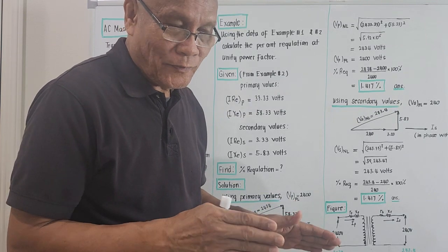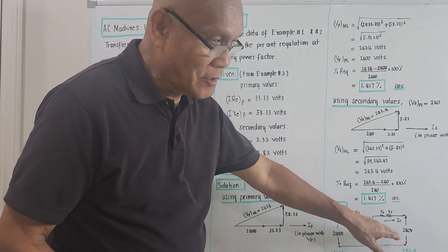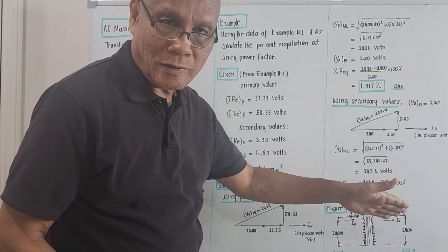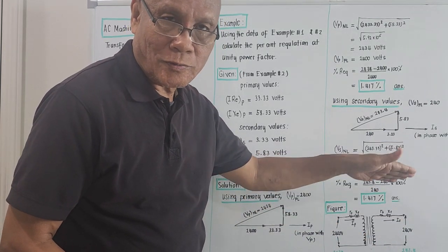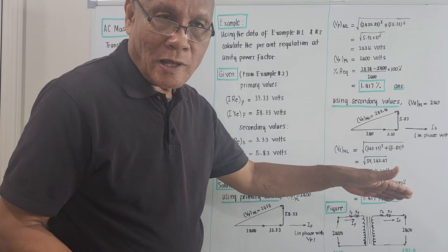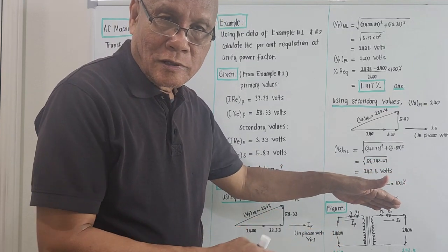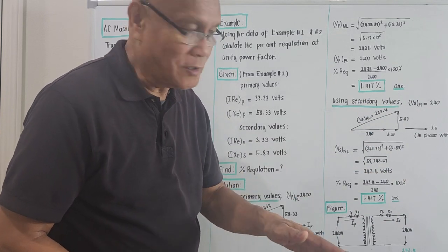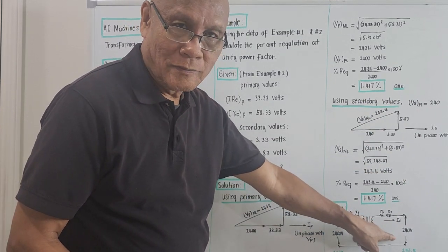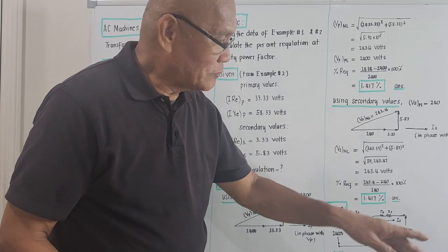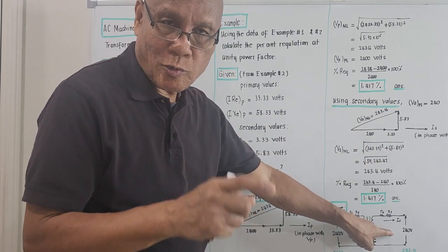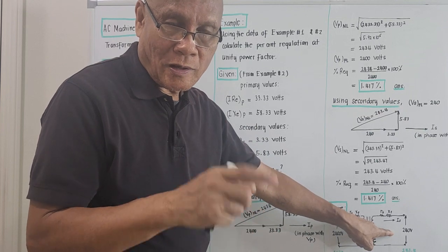So the given value should be higher than 240 at no load, then at full load it will reduce down to exactly the specification written on the transformer, 240. If it could maintain that value at full load, that transformer is very reliable,